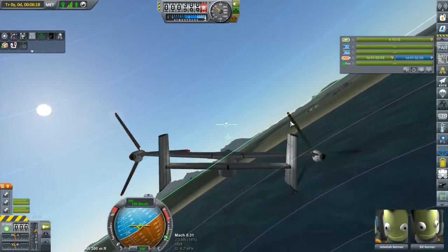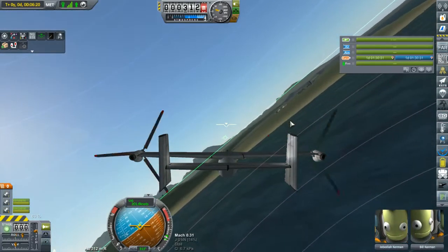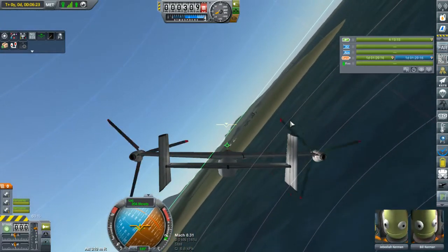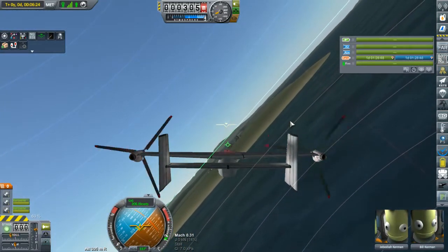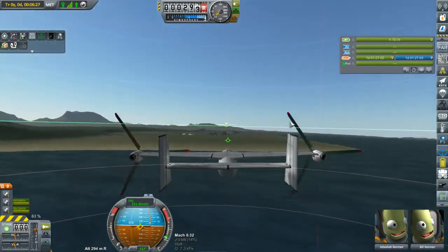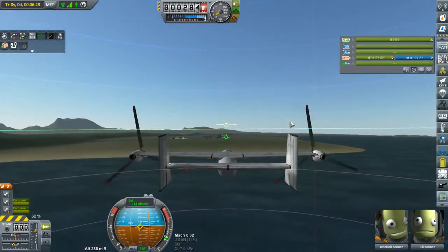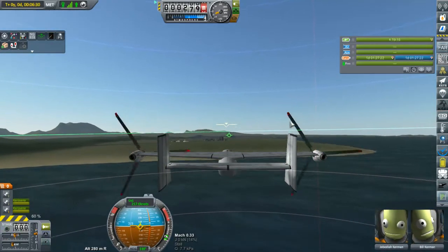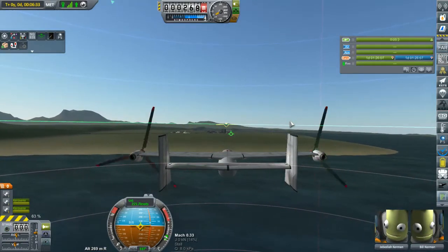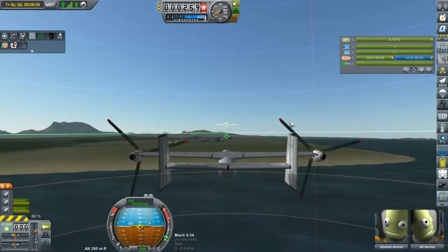And if you're wondering how well this thing performs in actually doing maneuvers, you roll this body over, pull back on the stick. We've obviously got a time slow down to about 60%. Let's correct out of a roll here. And I've turned SAS off and the thrusters off for forward flight. We're operating on regular control surfaces. A little bit of yaw kicks just to show that it does actually spring itself back into forward flight.